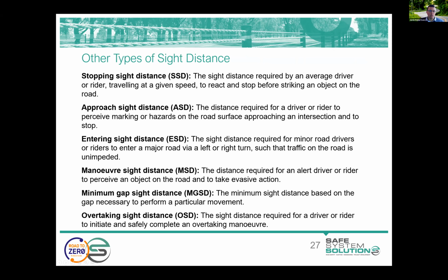I should mention that it is sort of increasingly common practice for sight distance check plans to be prepared and provided as part of drawing sets for road safety audits. So if that isn't provided, you're well within your rights to ask whether sight distance checks have been undertaken and ask for evidence of that.